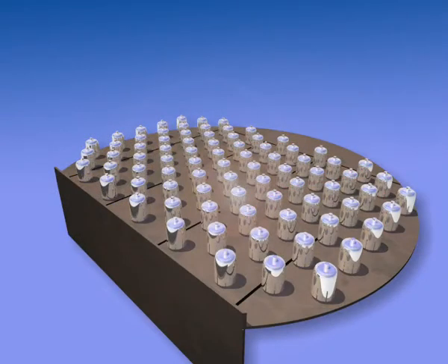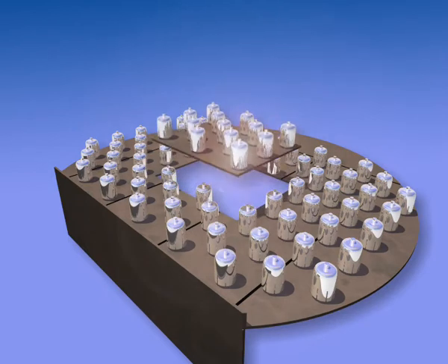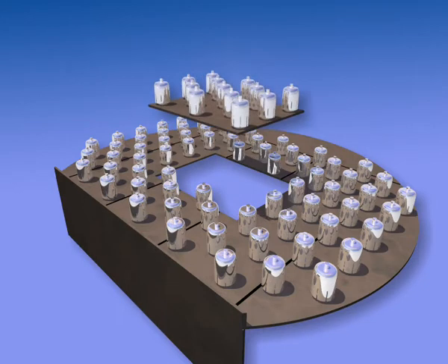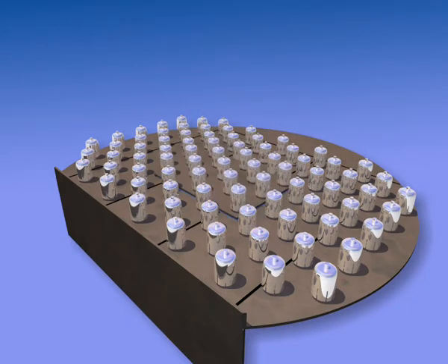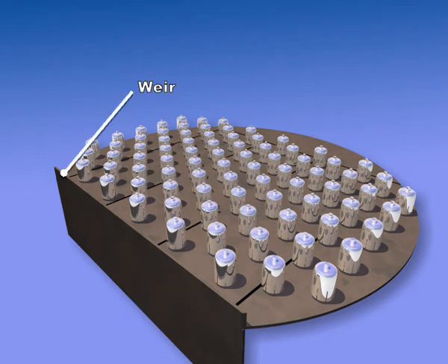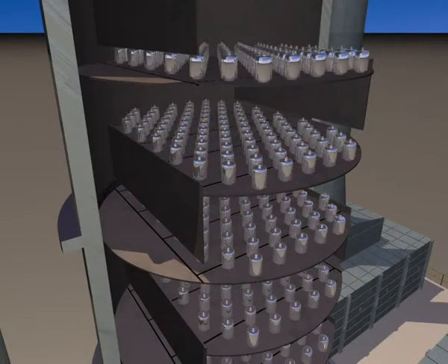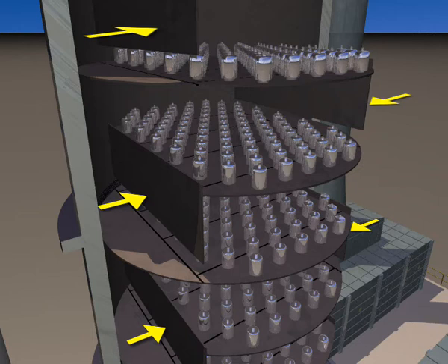Usually, trays will have a manway that can be removed and bolted back into place. The manway allows for personnel to climb through the tower when the system is out of operation for inspection, cleaning, or repairs. On one side of the tray, a weir is positioned right above the downcomer. Each tray is oriented at a 180-degree angle from the trays above and below, alternating the position of the downcomer from left to right as we move from tray to tray.